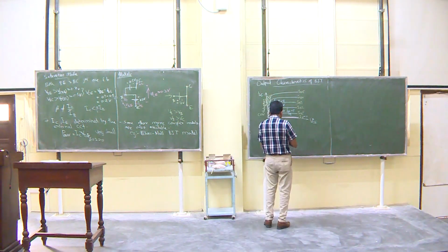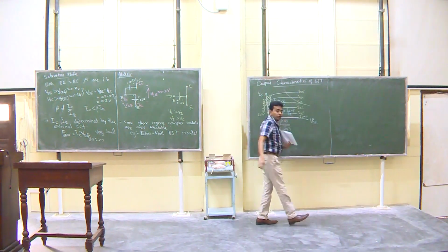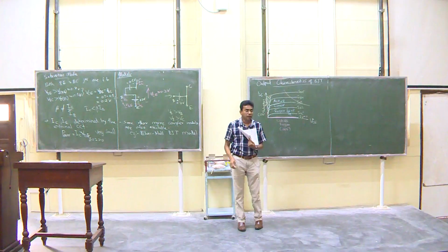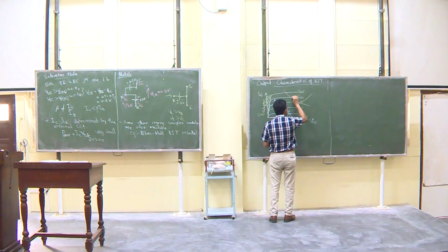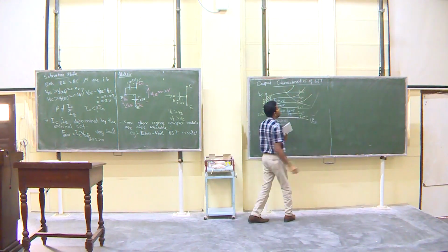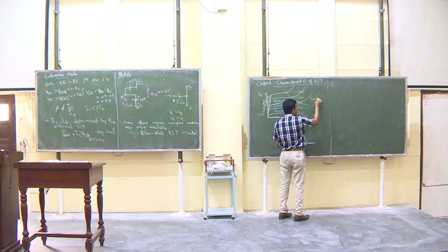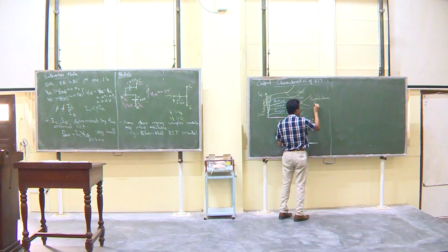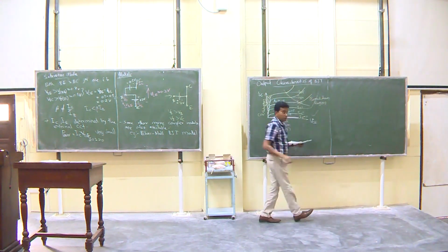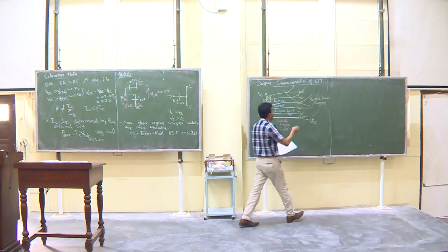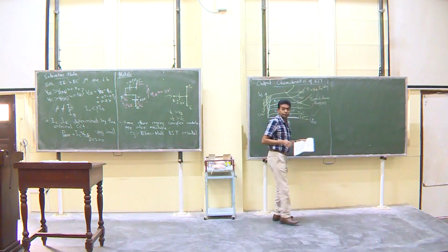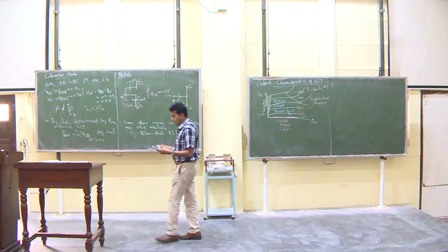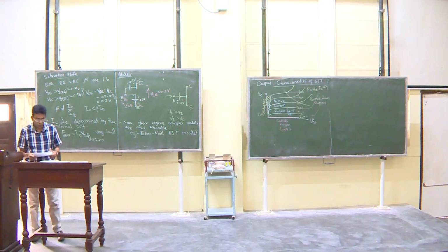So, therefore, there will be a region like VC times IC. If you draw a constant line, that is basically a hyperbola like that. So, anything above this is called the breakdown range. There, the power, VCE times IC, is much bigger, very high, right. So, that is basically called the output characteristics.